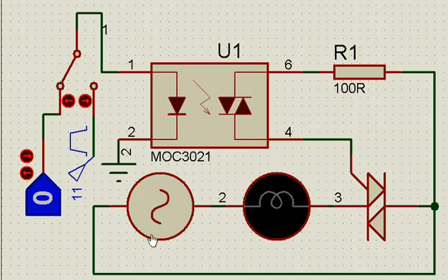Supposing for example, we will just see how it works, when this side becomes positive, supply goes this way. In the positive half cycle it goes this way, it cannot go this way, it goes this and then enters, and then it conducts only if the light is falling on this. Let's assume that the light is falling on this, so it goes this way and then enters the gate, comes out at the M1 terminal, passes through this lamp and then reaches here. And that is how the path in the gate and M1 is complete. Once the path between gate and M1 is complete, the current starts flowing, for that positive half cycle straight this way.